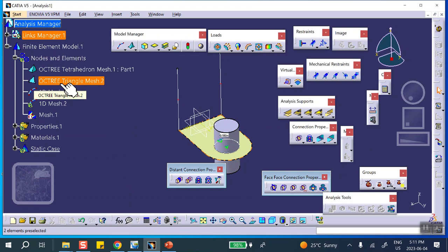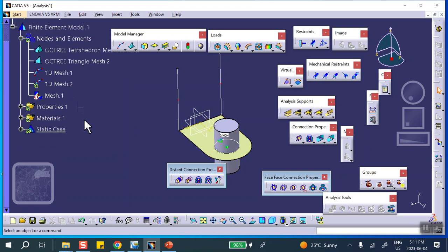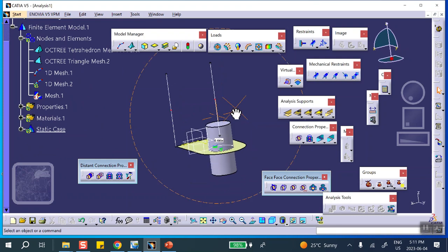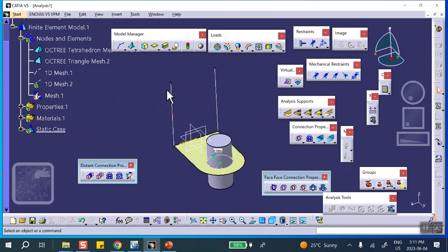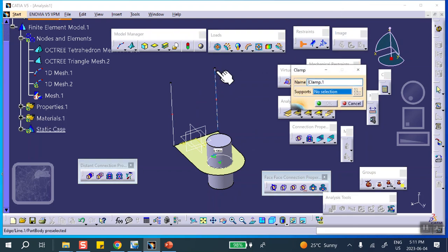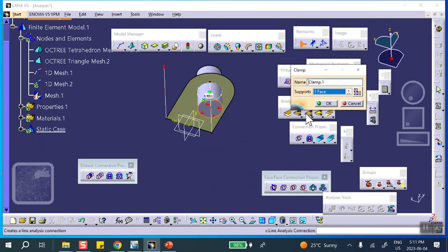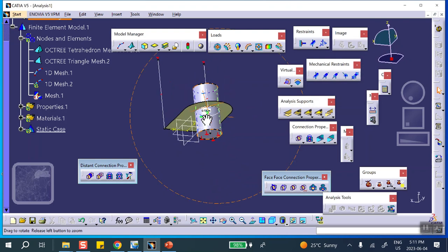All right, everything is made out of steel. We already did that, no problem. Okay, so now if you look at the mesh, you're going to see these meshed. Everything is meshed. So clamp that top point and this point and the bottom of that. Okay, very good.